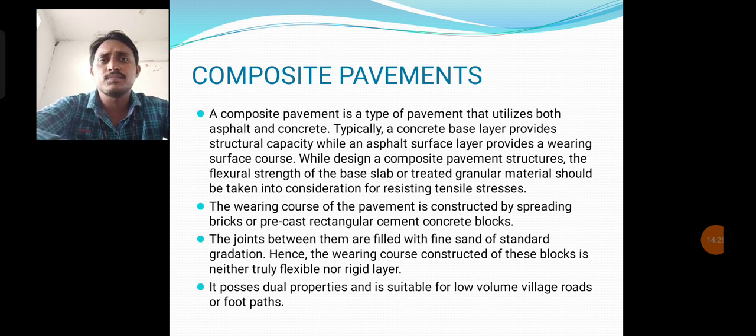While designing the composite pavement structure, the flexural strength of the base slab and treated granular material should be taken into consideration for tensile stresses. In the last rigid pavement also we discussed tensile stresses, and composite pavements also have tensile stresses. So the wearing course, or the top surface of the pavement, is constructed by spreading bricks or precast rectangular cement concrete blocks.